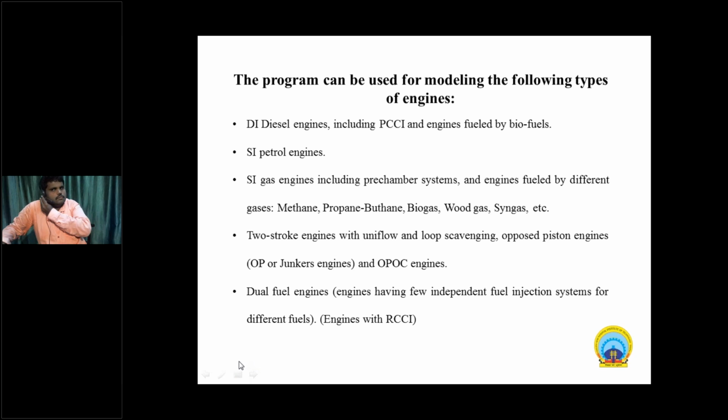The fuel spray evolution model consists of equations with dimensionless parameters to account for fuel properties and in-cylinder conditions. Specifics of the injection pressure profile and interaction of sprays with the air swirl and between themselves are also considered in this software. So the model allows engineers to carry out rapid parametric analysis, and the results of modeling for medium speed dual fuel diesel engines are presented.